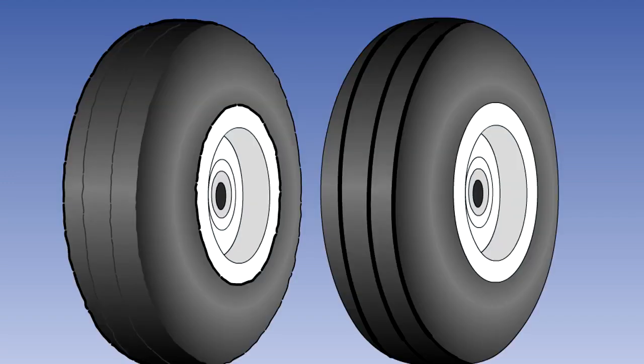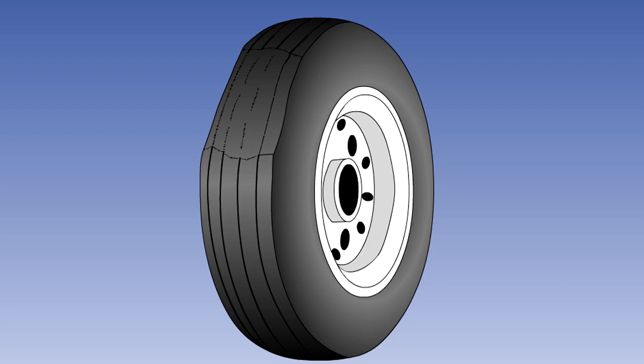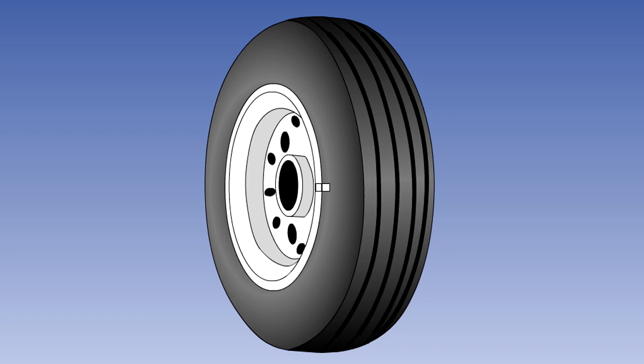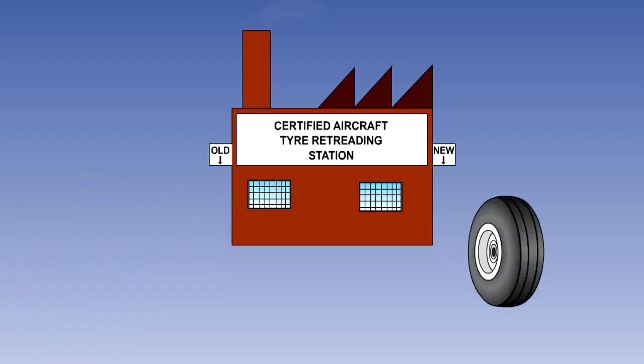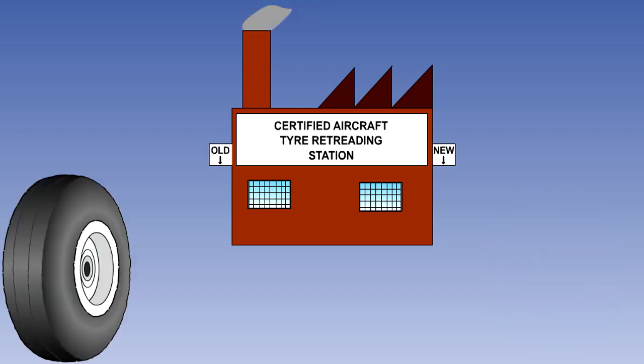You should now have a good understanding of how much tyre wear and damage is acceptable. The aquaplaning formula is quite important, but probably more important is the fact that if the tyre is aquaplaning, then its coefficient of friction is at or near 0. You should understand the problems associated with creep and how it can be monitored. Finally, remember that an aircraft tyre whose tread is worn beyond limits can normally be repaired or retreaded many times.